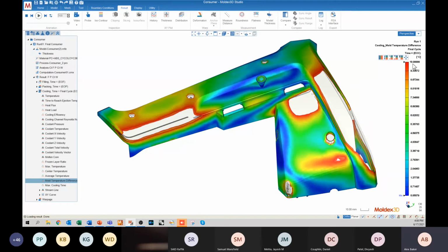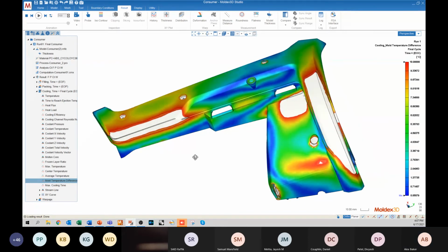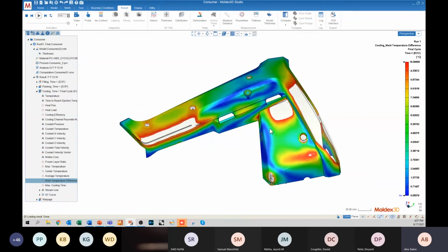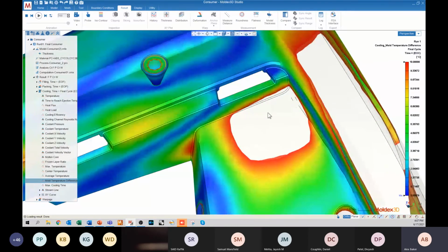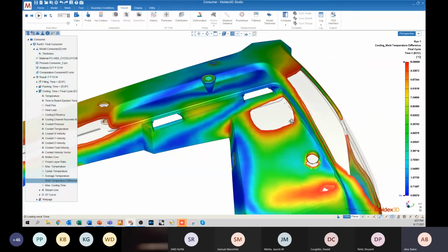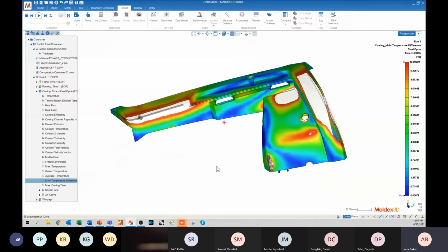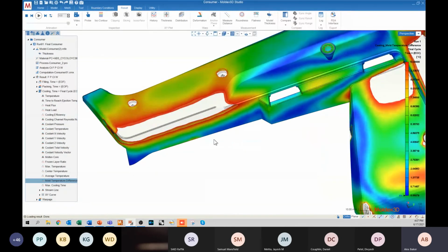All right, so any region that is greater than 10 degrees different from one another, that's what's shown as an uncolored region. Now you need to pair this with your temperature result to know which side is hotter, but we already knew this section here. We saw that this corner was pretty hot, so that's pretty obvious. We saw it in this feature, the bottom channel here was hot. We actually didn't see this guy at all, right? We didn't focus on this at all because it wasn't notable from the temperature.